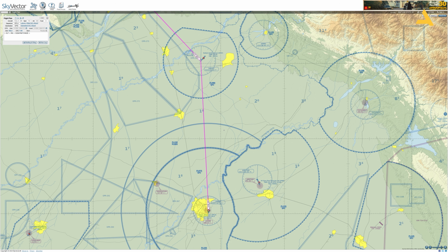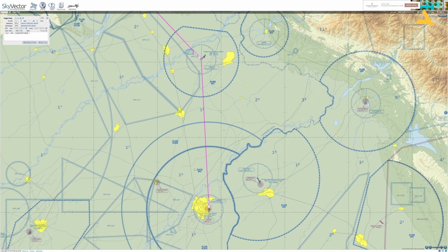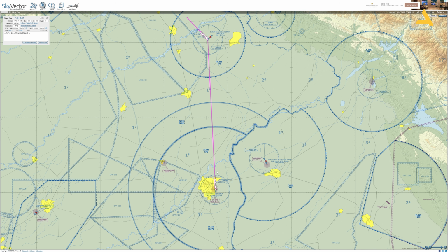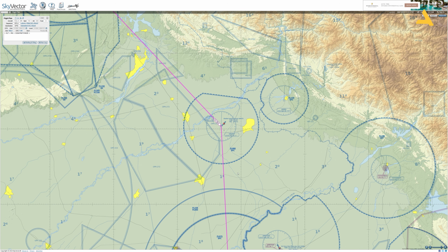Just plot this flight plan on Skyvector, and then just fly on this heading of 355. So right now for Lahore, your outbound radial is 355 and you are on this 355 radial. But for Sialkot, you're tracking the outbound radial of 355, but inbound is 175.